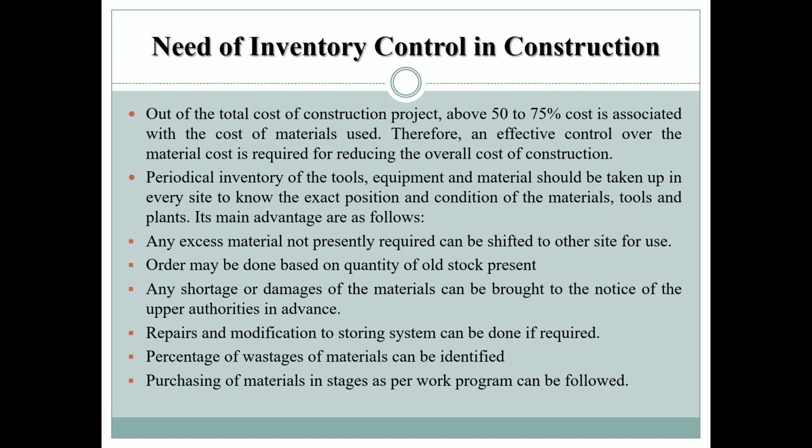So its main advantages are: any excess material not presently required can be shifted to other sites for use. And orders may be placed based on the quantity of old stock present. So based on the quantity of old stock, how much quantity I have in the stock, based on that I can order other materials. Any shortage or damage of the material can be brought to the notice of the upper authorities in advance. Repairs and modification to the storing system can be done if required, and percentage of wastages of materials can be identified. Purchasing of materials in stages as per work program can be followed.